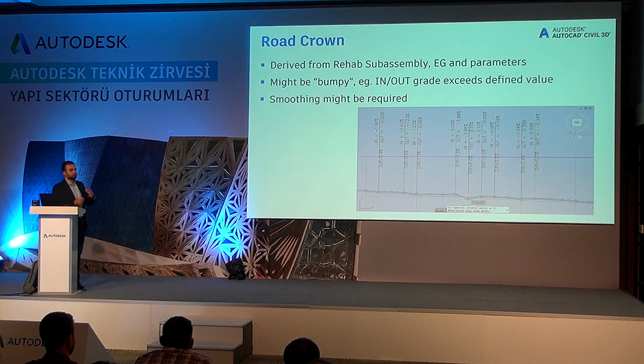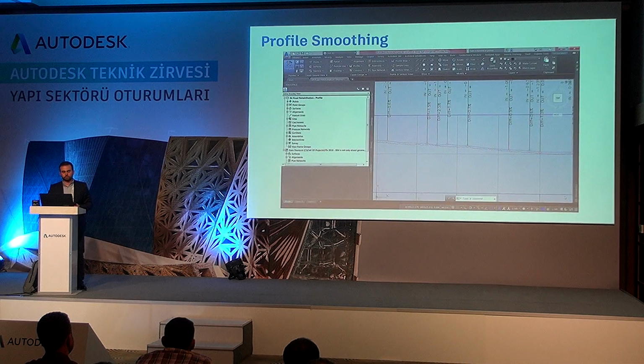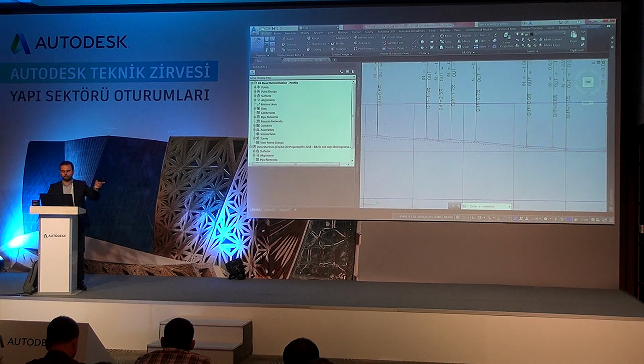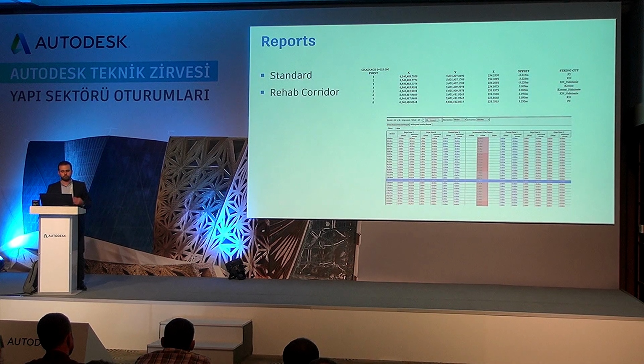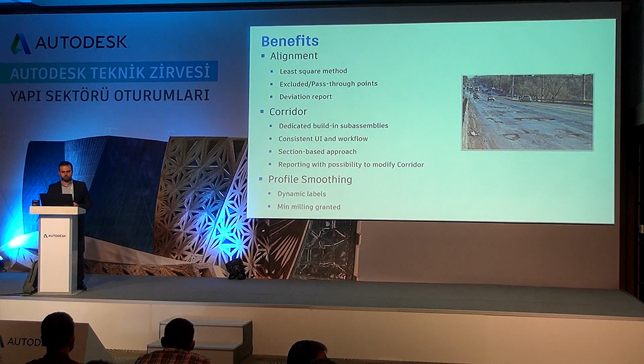So this is where it's a good practice to put some annotation, conditional annotation, so if the grade or slope is less or more than a certain criteria, it will highlight it for you, and then you can make those tweaks automatically to save on time. Hopefully in the future, Autodesk will make this process also automated. With a single click of a button, it will be automated altogether. And then you can generate tables, cross-sections, to check that your design meets the standards. Definitely other tables as well.